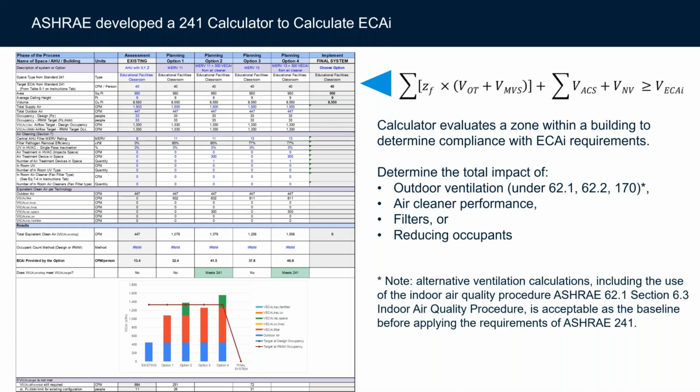So if you do nothing, it will populate the VRP parameters. And then you get what your supply area is, what your outdoor area is, and so on. And so that then begins to calculate your IRMM just with outdoor air. And then going down into the next section, you start to look at what quality filters you have, what is the UVC, are you using UV in any of these spaces, and then the next section are any additional equivalent air cleaners that you're going to provide. And then that gives you the basis of design for what it is you're going to design.